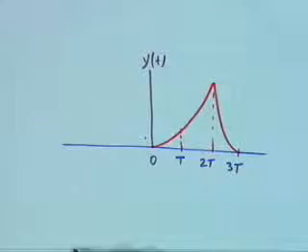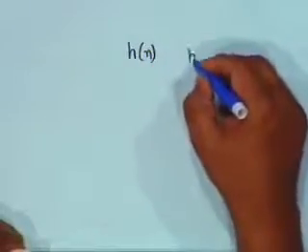Now this is an example of convolution in a linear time invariant system. One of the main reasons why linear time invariant systems are so popular in terms of analysis and synthesis is that they obey convolution, and the output is very easy to find in terms of the input, arbitrary input, provided you know either h of n or h of t.